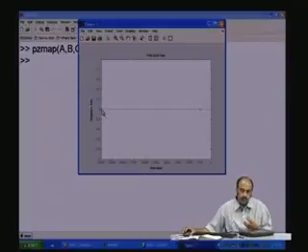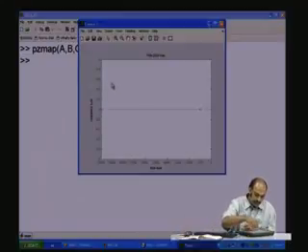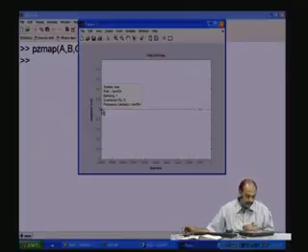In fact, now you can place the pole accordingly, so that you get an idea of what these damping things are. The character of this pole here, the overshoot would be 0%. If you place it here, damping is 1, and you get the frequency and the pole positions.